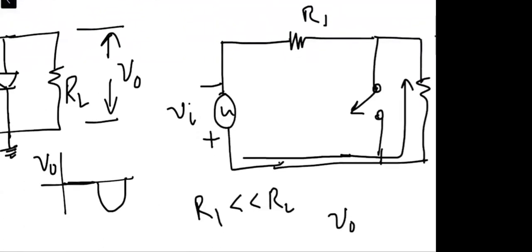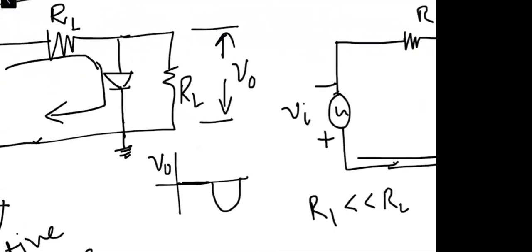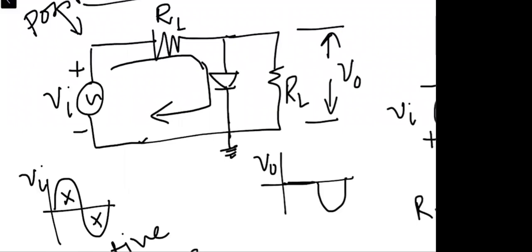For the positive half cycle, we said the diode was behaving as a short circuit switch, right? So in that case, to overcome the barrier potential in case of silicon, the barrier potential is 0.7 volts. So the output over here for the positive half cycle will be 0.7 volts, right? Are you with me?